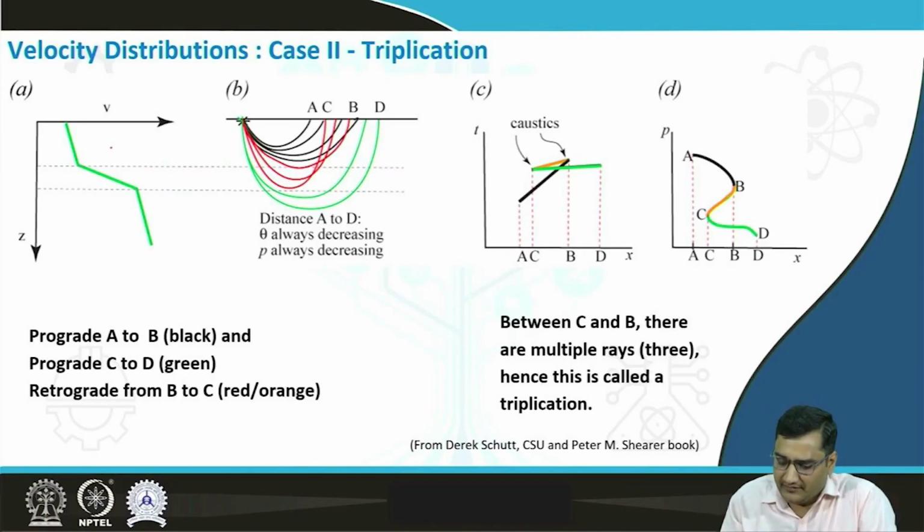So this is your velocity profile or velocity model, and velocities are smoothly increasing, and then there is a sudden increase in the velocity, and the velocities are again smoothly increasing. And this is your source, and you can see that the rays in the zone above the high velocity zone are going and being recorded at the stations on the surface.